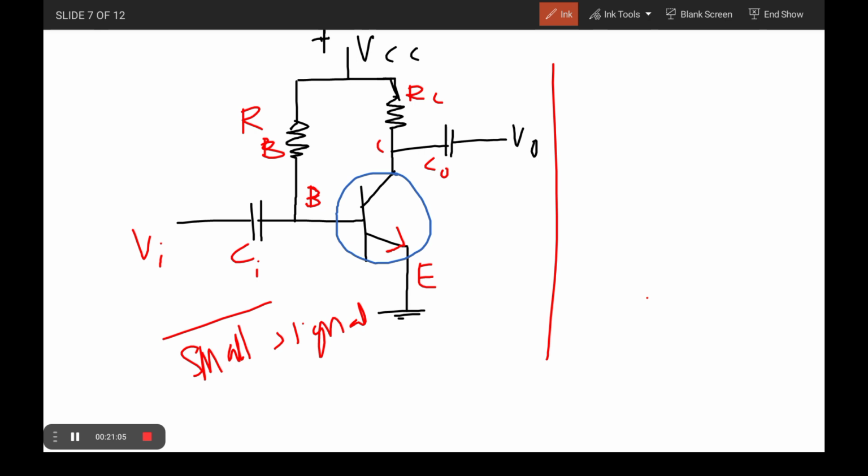These are generally called the biasing elements. These biasing elements set the Q point of the transistor. Whenever the Q point is set, it behaves with some resistive nature. Therefore, the AC signal can pass through the transistor without any degradation.